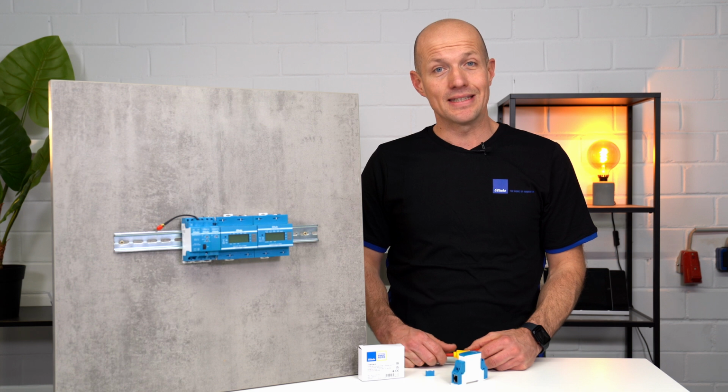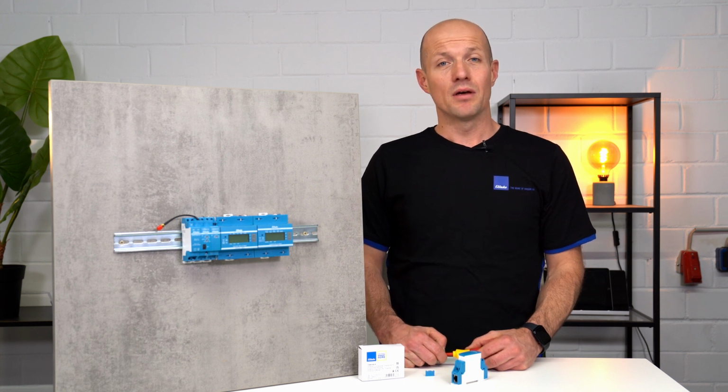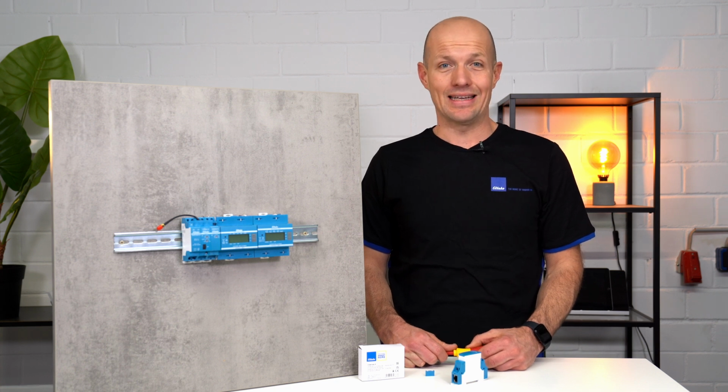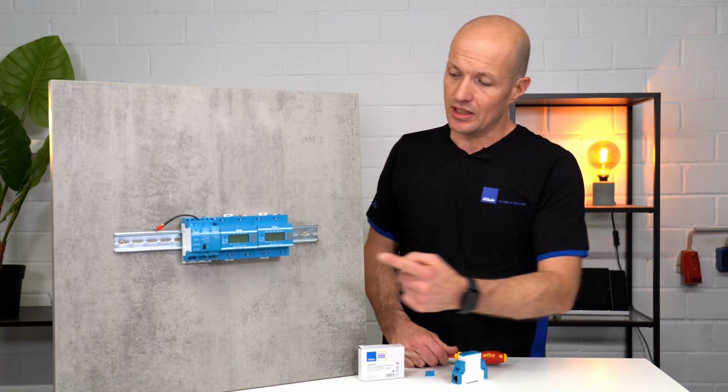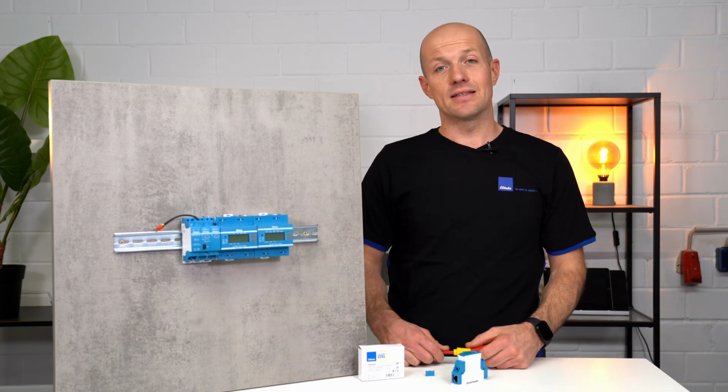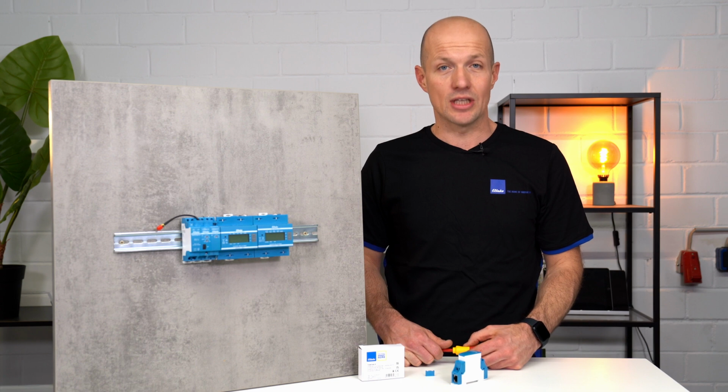Once you have properly commissioned the Series 14 bus, you still need to assign a device address for each subscriber or meter. This can be done conveniently via the display for Series 14 3-phase meters. With other devices, you may have to do this using the built-in adjusting wheels.